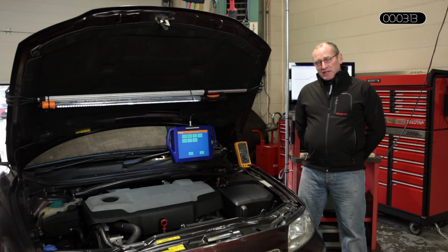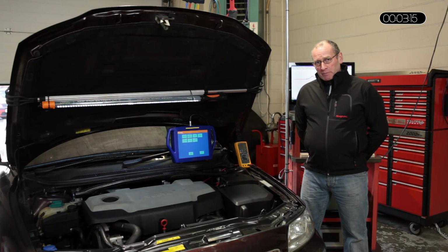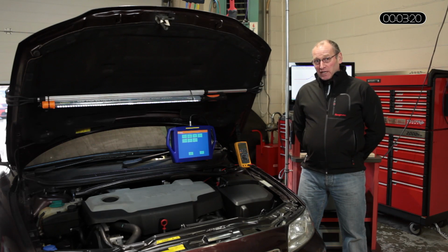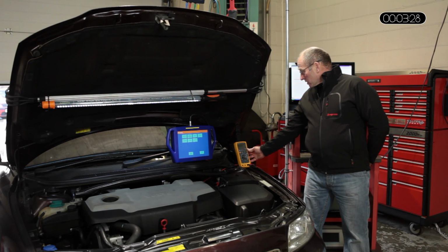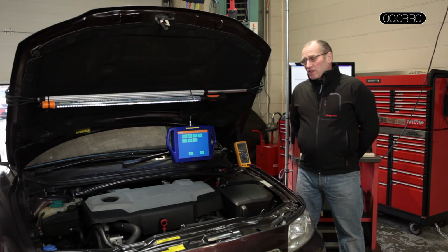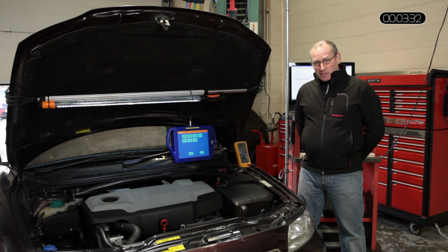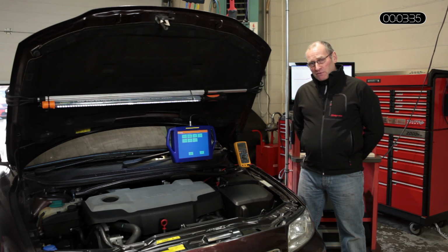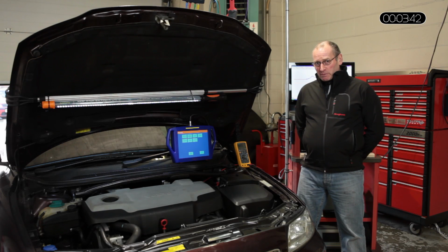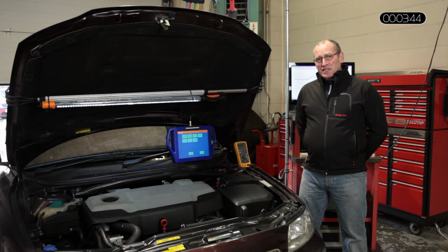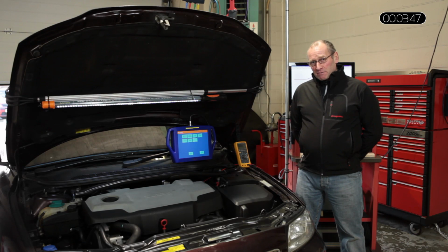So first of all, we carried out what we call a plausibility check. With the ignition key on, with the engine static, not running, you should have around 0.6, 0.7 of a volt. We'll come back to that later when we use the actual multimeter. This vehicle did have the correct voltage, around 0.7, 0.74, key on static. With the engine at idle, it also remained at the same figure, which it should do. So initially, it didn't indicate a blocked DPF.